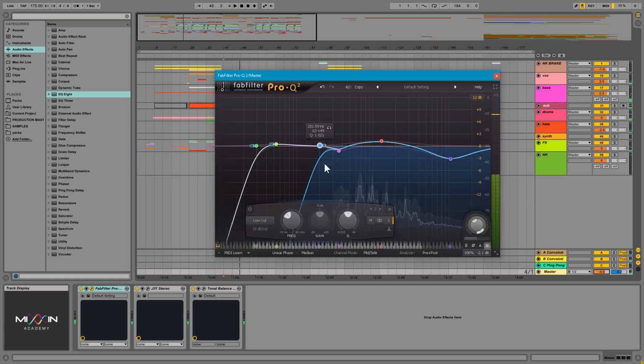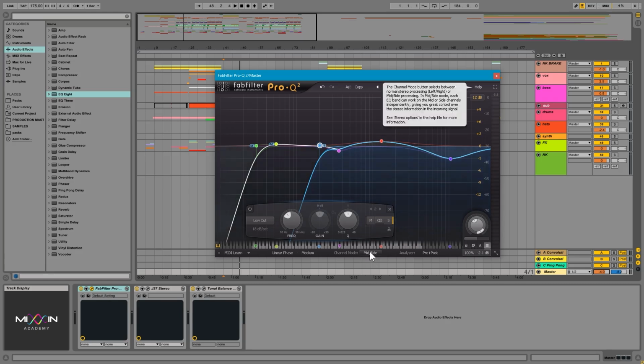You see, so I'm making sure that none of those low frequencies from all of those basses are going to be there and maybe potentially make problems once this is reproduced on maybe a mono system or a system where actually only the bass is monoed out to be routed into the subwoofers and the subwoofer section of, let's say, a large PA. So this is one of the usages, of course, that we can use this for, and this is one of the plugins that actually has a capability inside on its own to give us mid-side processing.